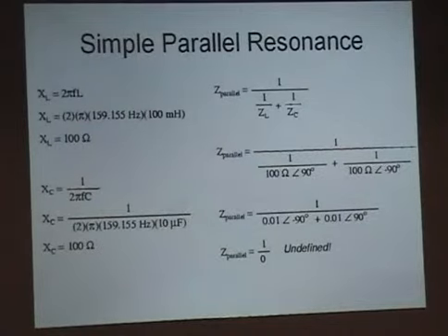This is your standing wave ratio, why you want to keep it lower. You get more power at the antenna, and it goes into radiation resistance instead of into your inductive or your capacitive reactance. You want it to go out. That way you get more radiation, and people hear you. So this is just the inverse of what happened back here. If I showed you the equation for this, or showed you the chart for this, you'd see a big dip right at resonance. In this case, you see a big peak.